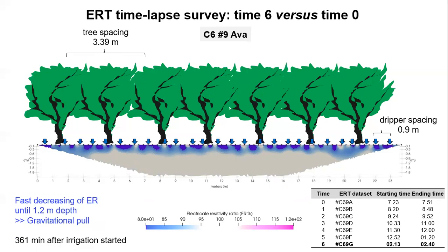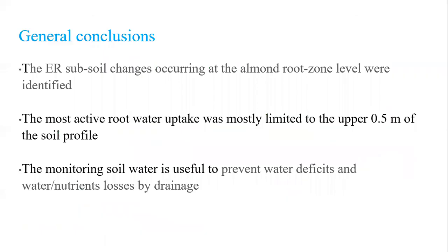So this demonstrates the fact that we cannot manage these soils the same way, because one is going to infiltrate faster. If you apply more water, most of it is going to be lost through deep percolation. And for the heavy soils, we saw that the infiltration rate is much smaller than the root water uptake rate.